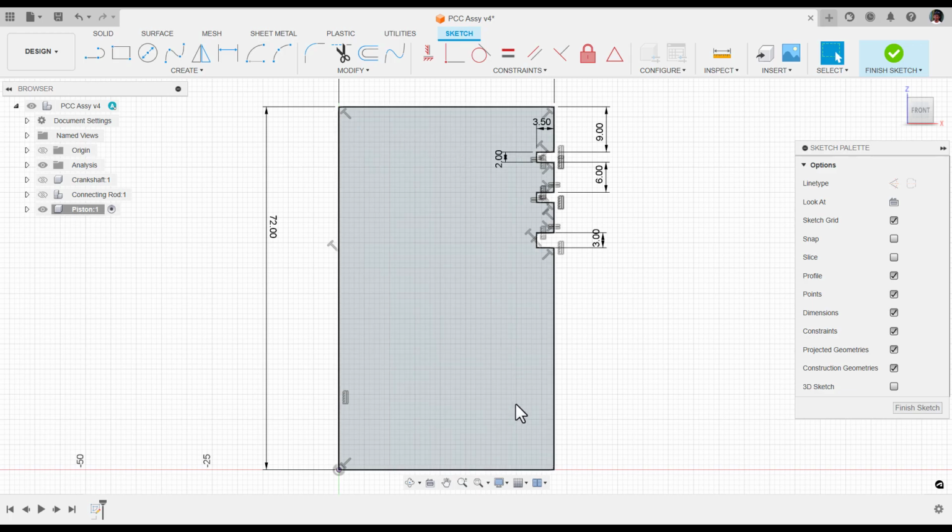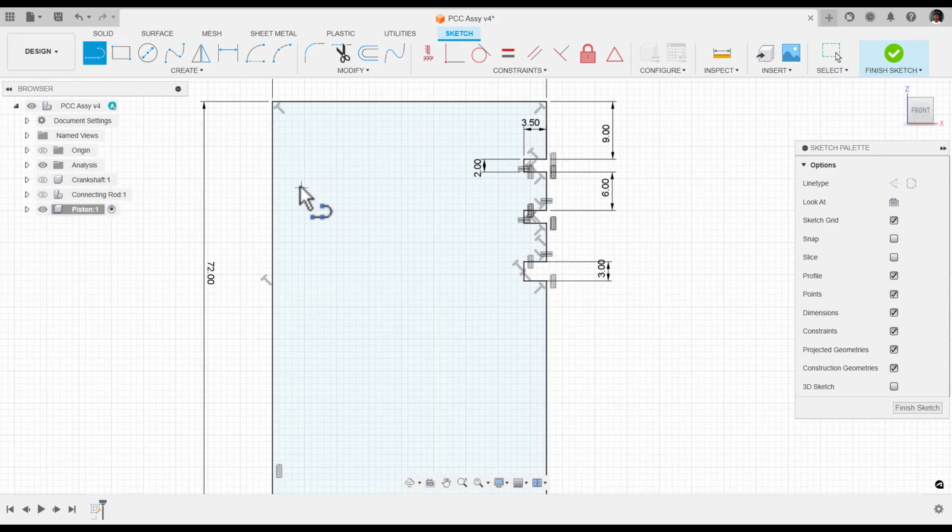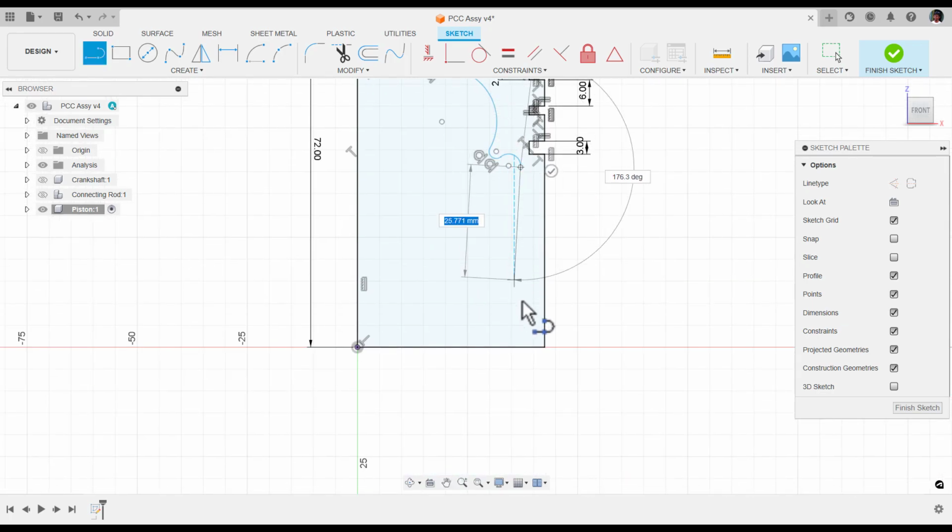Now let's draw the inner profile, so that we will get our profile for the revolve. We can use the axis to make it 360 degrees. So, just observe, this is very important. A simple line from this point just like this. Hold your left mouse button to get the curve and simply bring the curve like this. One more curve just like this, and again one more curve just like this. All will be applied with tangents. If not, you just apply it manually.